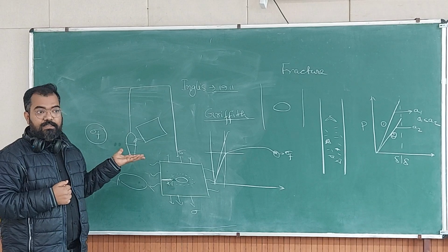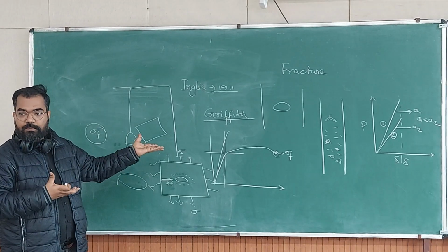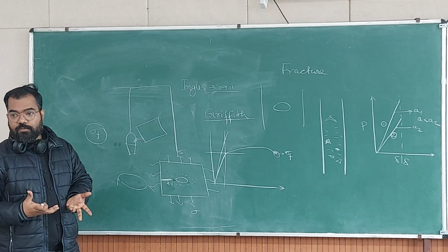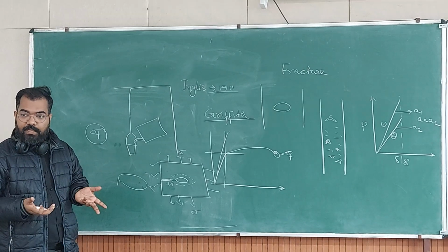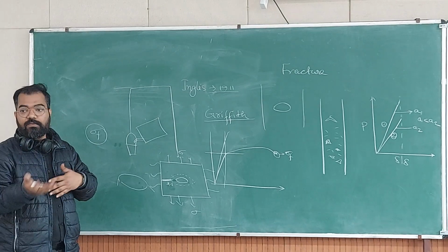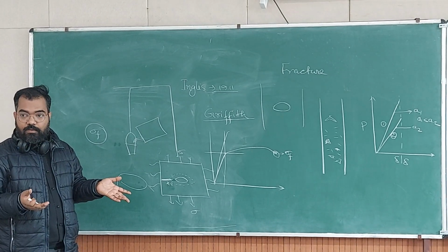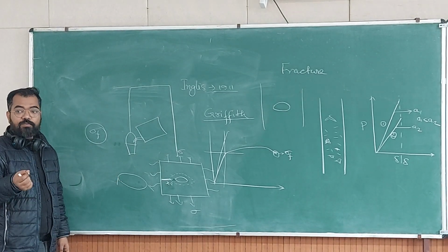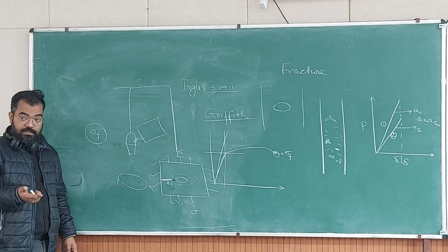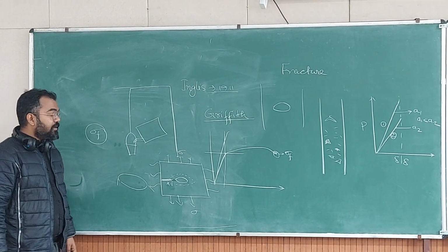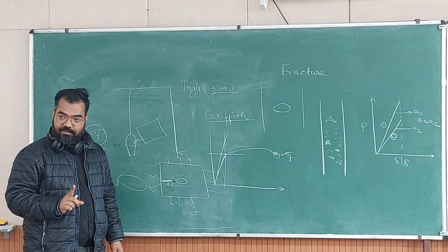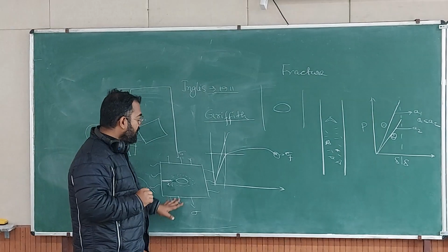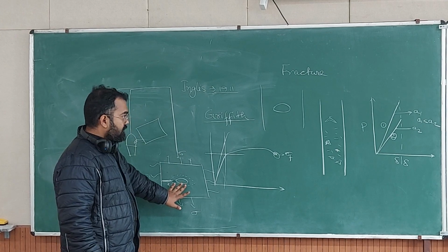Okay? So when you test cast iron or something very brittle, for example graphite, it's not going to consume any energy plastically, right? So everything is going to be elastic and then fracture, no plasticity. Whatever plasticity is there is so small that it cannot be measured. What you are saying is correct, but that is in the future. That happens after Griffith. Okay? Good. So where were we?